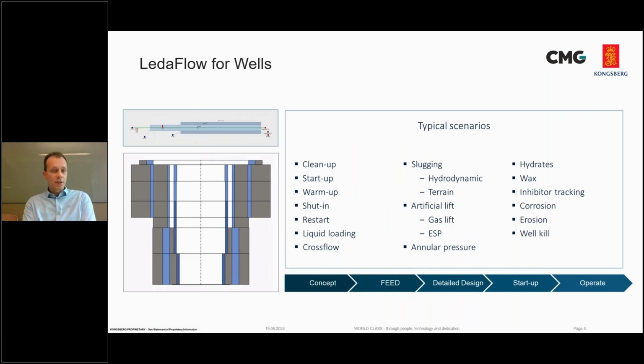Then LedaFlow for wells. This shows some of the typical scenarios that you can simulate using LedaFlow. In LedaFlow, you can build a quite detailed well model, not only modeling the flow inside the tubing, but also the flow inside multiple annular spaces around the tubing.